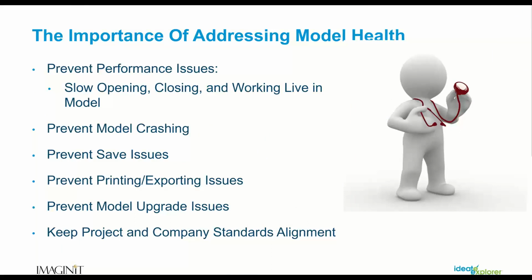All right, so why is it important to have a healthy model in Revit? Well, let's start with things that are performing slowly: a model that is slow to open, slow to close, slow to work around in, and slow to save. These are good trends that tell you your model needs a health check. Basically, you want to have your model streamlined. It's never fun when you're dealing with models that are crashing, and that's a good reason for a health check.